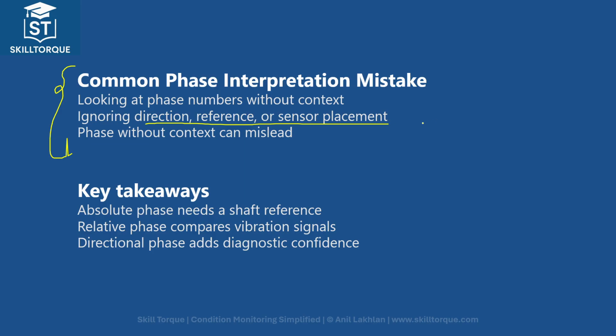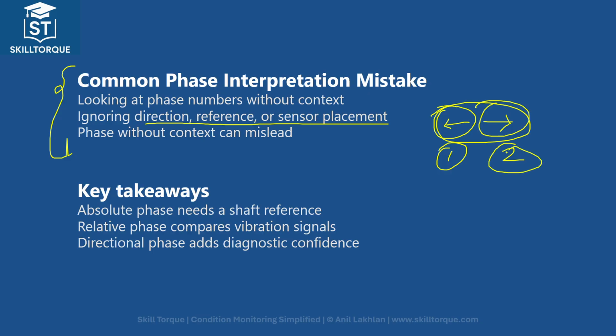Normally, let's say you want to check whether this machine is having misalignment issues or not, and you have placed the sensors. Normally, to diagnose misalignment, you put one sensor on the axial side of the motor drive end, and another one on the pump drive end, right? In that case, sensor A's face is towards the left, and the other sensor, sensor B, is facing towards the right side, right? So the sensor orientation is different. One is facing towards the north, another one towards the south.